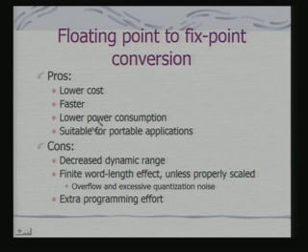But why is fixed point conversion done as part of computation units? If you remember, many of these processors do have support for fixed point arithmetic. Even the DSPs have support for fixed point arithmetic, and for higher cost DSPs you have floating point support. Now, if the precision you require for your application is good enough to be done with fixed point arithmetic, then it is better to go for fixed point arithmetic.